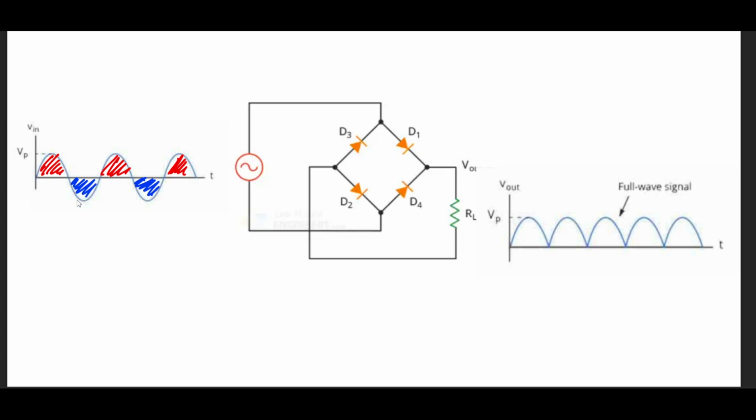So the positive current is going to leave this terminal, then towards this side, towards this side, towards this side. Now when it reaches this terminal, it realizes it can go towards both sides. It can either go to diode 3 or it can go towards diode 1. But we understand that diode 3's direction does not match the direction of the current that is being expected. So since the directions are opposite, I will say that this is reverse biased and the current will not flow.